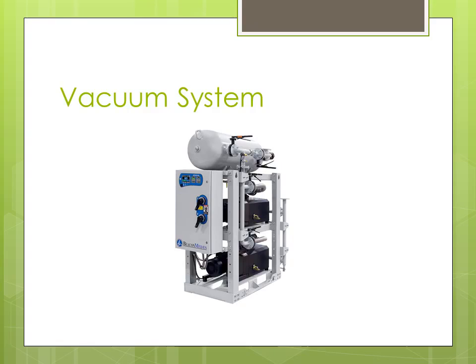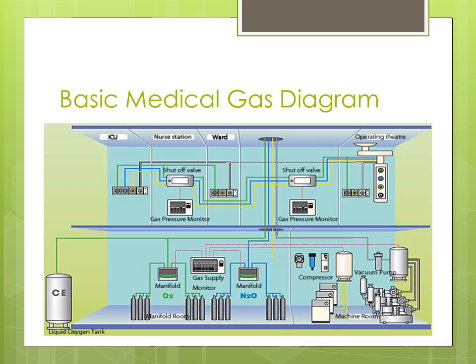or it can be you have the system designed so that you have enough capacity where, let's say you have two motors or two pumps that are running, and you have enough capacity so that if one were to fail, the other one has more than enough capacity to cover the load. So it doesn't necessarily mean that one isn't running. It could be both are running, or it could be that you're alternating back and forth. But in any case, you have one extra, and you'll hear N+1 quite a bit as we go through maintenance and operations and even codes and standards and design. So I just wanted to mention N+1 while we're at this point.